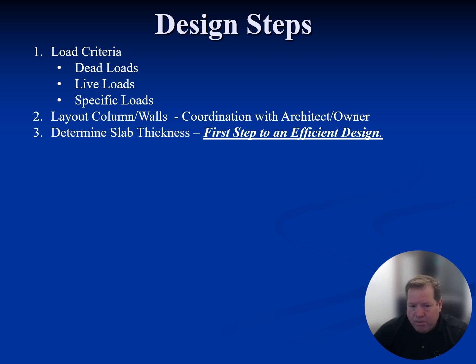I think probably the most important thing about PT design, aside from knowing what you're doing, is the slab thickness. With the software out there, there are lots of brands, a lot of great pieces of software. If you get the slab thickness right, you're going to have to try really hard to screw up. You can still do it, of course, but the slab thickness being the right thickness, plus or minus, is almost going to ensure a good design with the software that's out there.